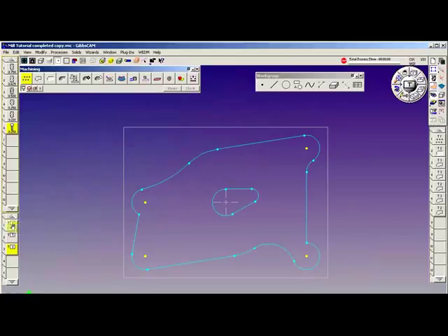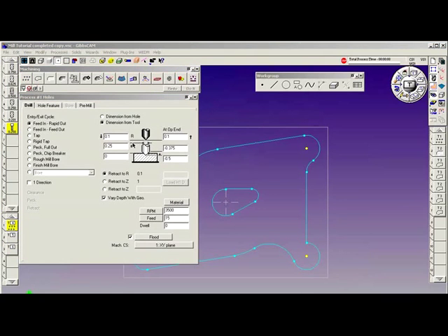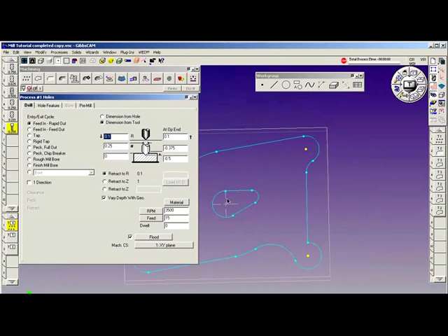The holes process for tool number 1 is going to be a spot drill. Feed in, rapid out. Now, what we're going to do is make the R plane down at the bottom from the top of the cut. I'm going to make this at -0.4. And I'm going to tell it that the stock or the cut begins at -0.5. So it's going to rapid down to 400 thousandths inside the pocket. It recognizes the top of the cut at -0.5. It's going to retract to 0.1.